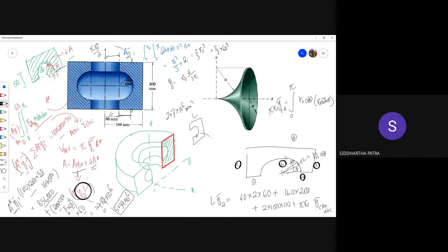Okay, so essentially the r0 squared comes out of the integration because it's a constant, and you are simply doing sine theta d theta between 0 to pi, and as we discussed earlier, this is simply 2. So the y bar for the circular arc is twice r0 squared divided by pi r0, so basically twice r0 by pi. And that expression is quite different from this one right here.